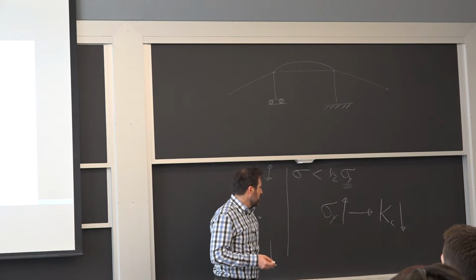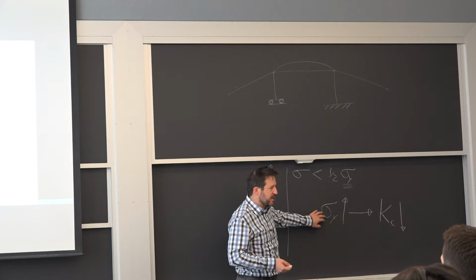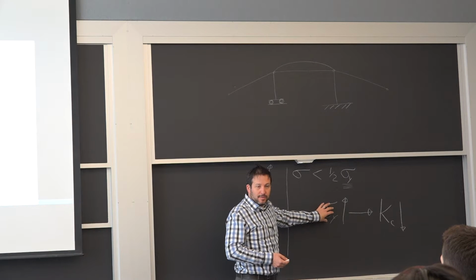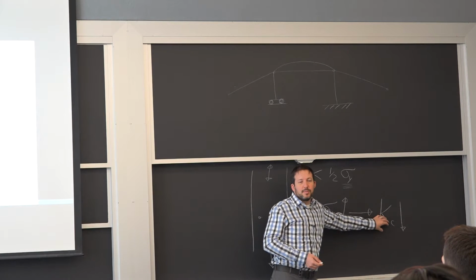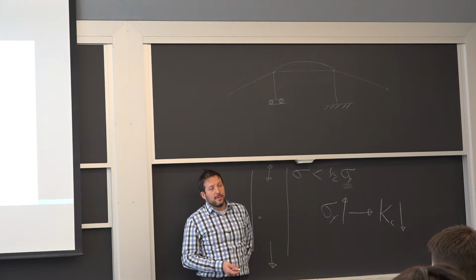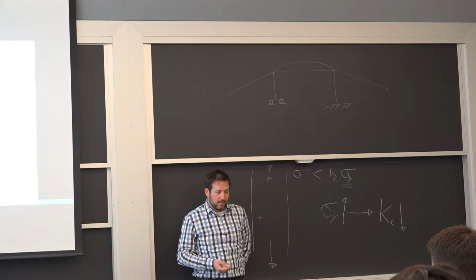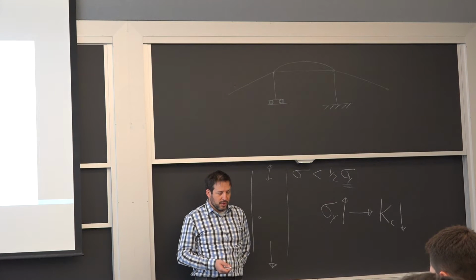But the idea was to try to be a compromise. Because if you go too far, you take a ceramic, just at the extreme, your fracture toughness is extremely low, and you lose overall. So it is a compromise between crack initiation and the resistance of something that is cracked to an overload failure.